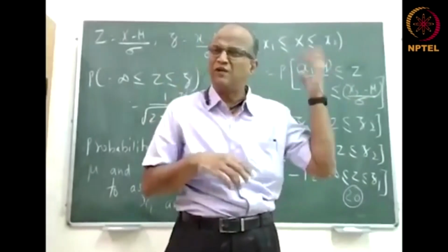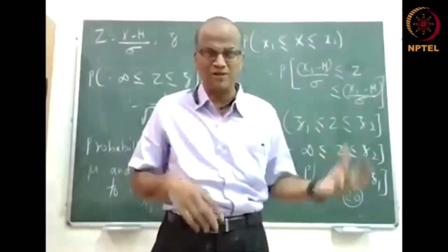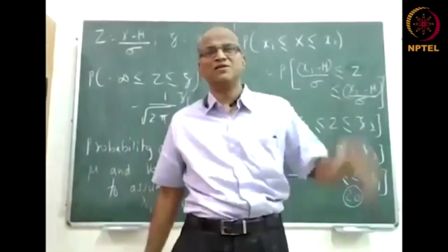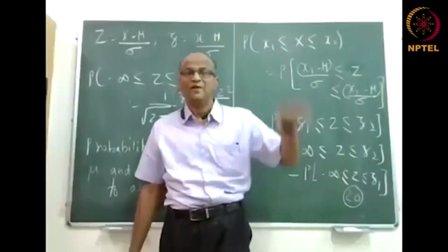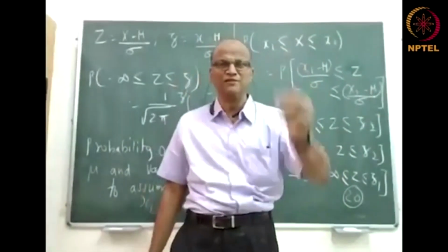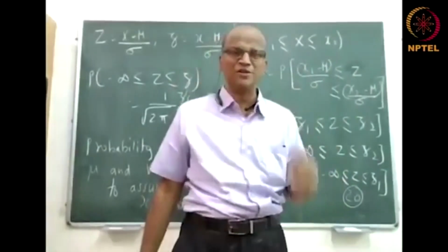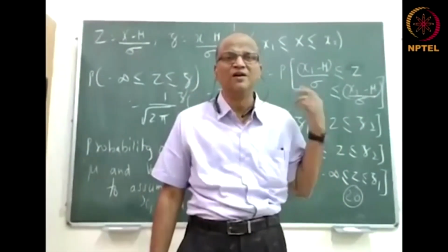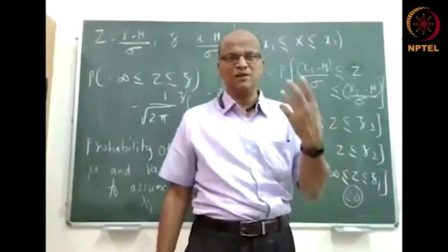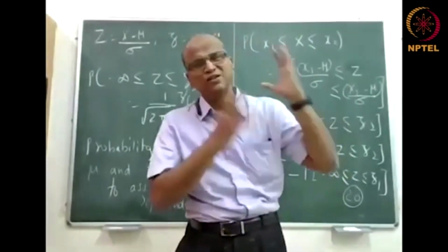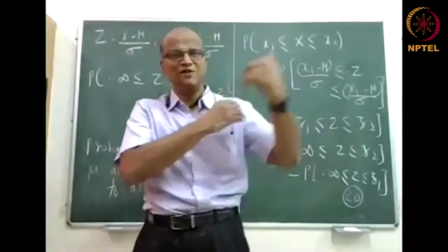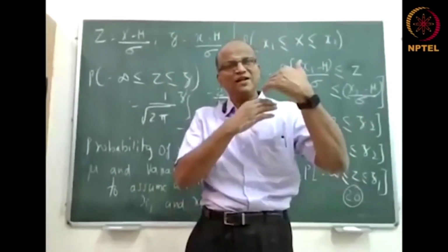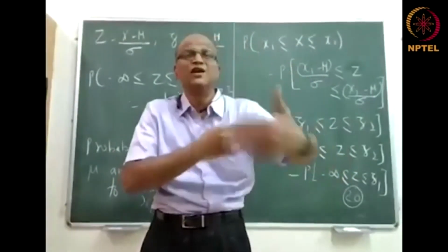Forget about the data, forget about the theorem, forget about Gauss. What is the manufacturing process you are using to make the shaft? How much tolerance and accuracy will your machine afford? Then there is human error in the measurement, and human error in the calibration. So there is a natural variability. Regardless of your high-funda statistics, it cannot get past that. The data is only as good as the model.